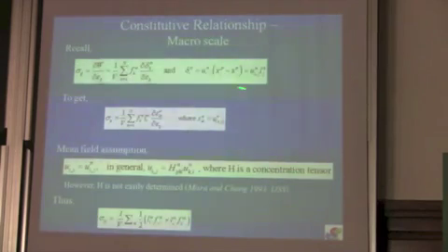So we have the local constitutive law. We can now use the macro scale stress, or the Cauchy stress expression we derived a few slides ago, and complete the constitutive relationship at the macro scale. Here I want to make a comment: the stress is given not only in terms of intergranular forces, but also this partial derivative of the local displacement with respect to the overall strain. If we define the local displacements to be proportional to some local strain, which is valid only at the grain scale, then we have to think about this term. In other words, at every grain level the strains are fluctuating, and they have some relationship to the overall strain of a collection of these grains.